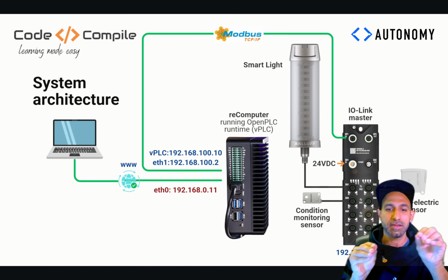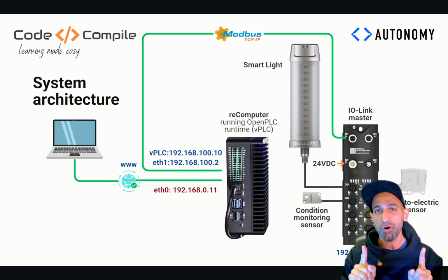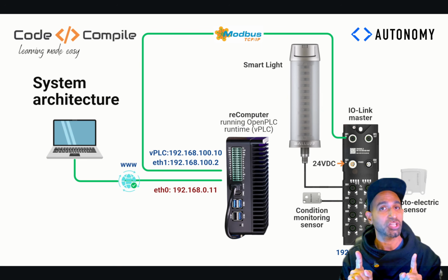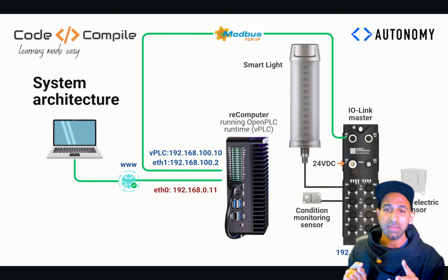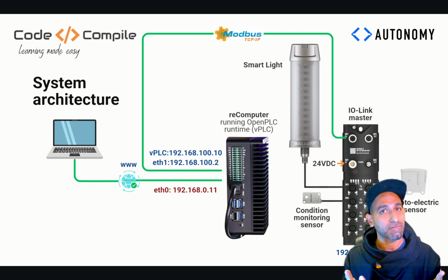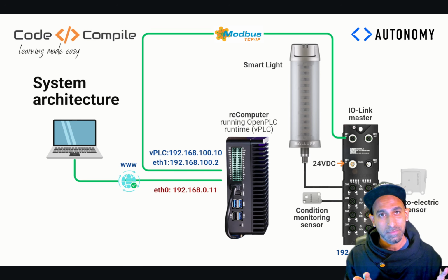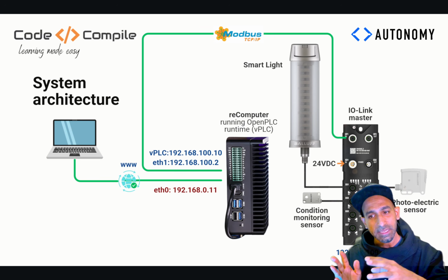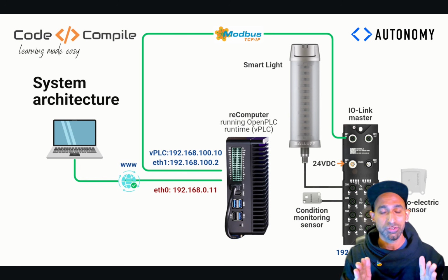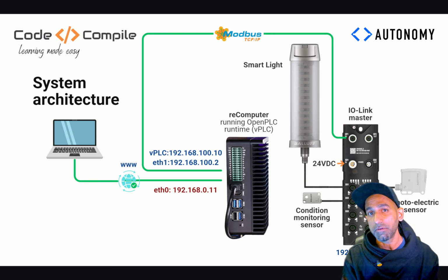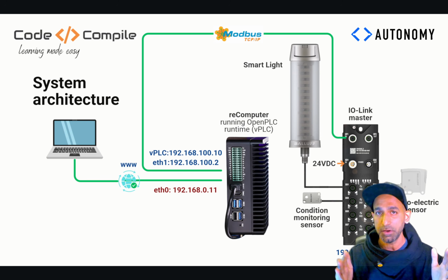Now, how to get this data to my PLC? Now remember, I'm using Modbus TCP/IP. And this is a very fast communication, but this comes with a challenge. The challenge is the data that I'm reading in my IO-Link master from a vibration sensor is coming in float. So you can see the value I've shown you before. But when I'm sending the value via Modbus, you can't send via float. You have to send in integer. So I am sending the value in integer, but then I convert it back to float in my PLC. So I will show you the program, how you can do that. You can also take a copy of my logic. You can implement the same code everywhere where you want to use.